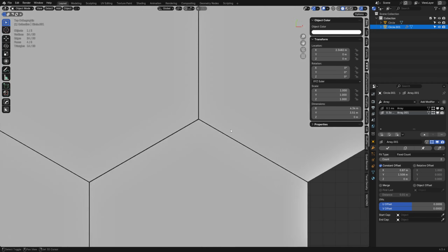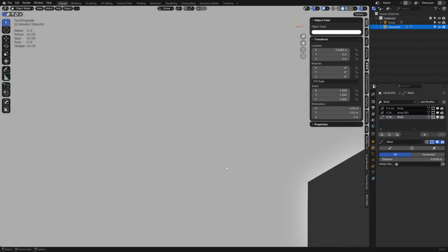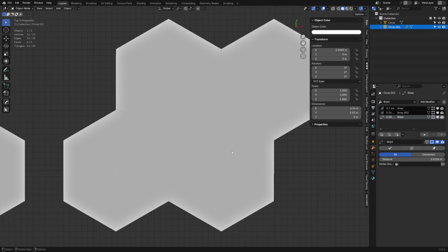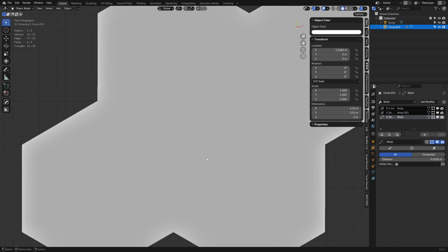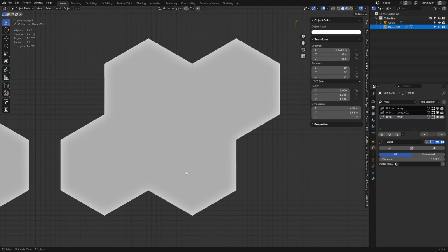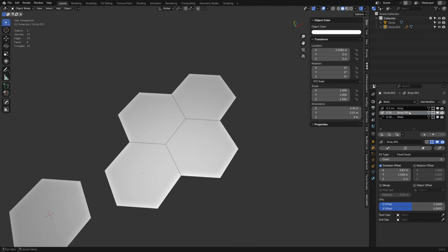There is a gap. So to get rid of that gap, you could merge with each array or you can add a weld modifier and crank up the value a little. The closer they are, the less this value has to be big. So if you're ever doing holding edges with subdivision and whatnot, you can have smaller edges. Nicer that way. Not very precise, but it does work. So wanted to go through that real quick. And so this is how you generate this pattern anyway.